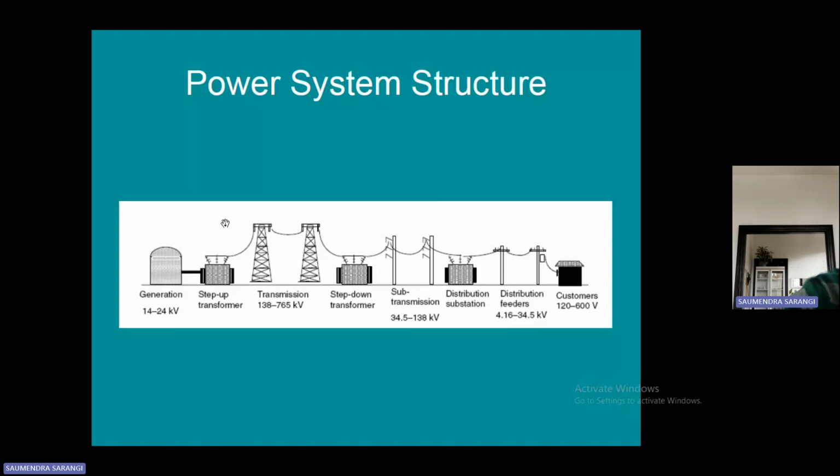However, in the upper area where we are talking about the transmission system, where the transmission towers are there, we use distance protection. And before that, we'll be using the transformer. The transformer is connected to the generator. Then for the generator and transformer, multiple relays are available. Overcurrent is available, differential protection is available, then under voltage relay, under frequency relay, and the Buchholz relay is used in our transformer. So many things will be there.